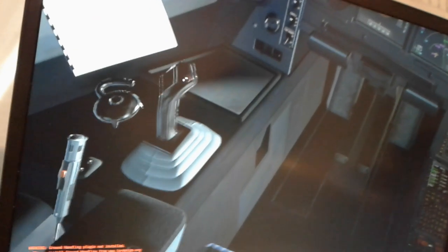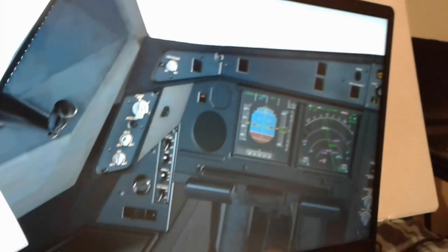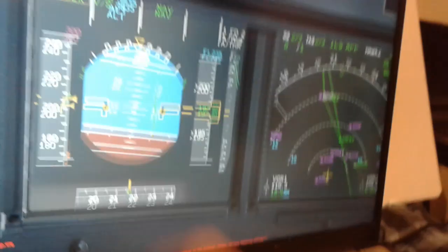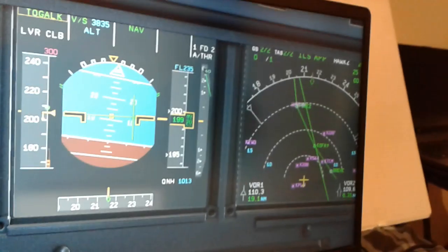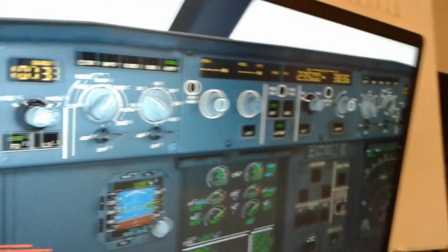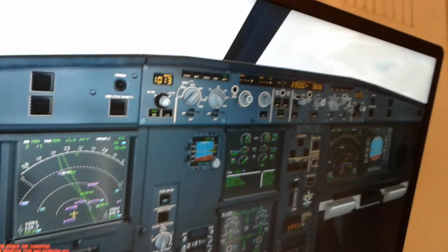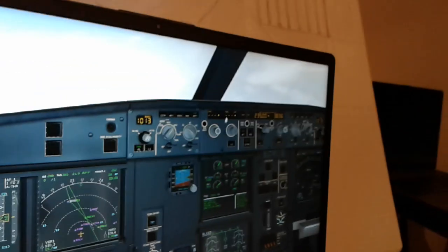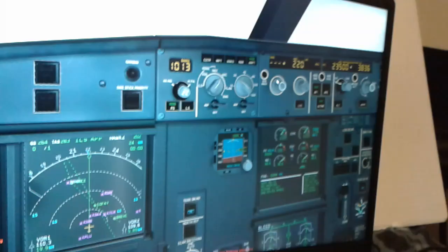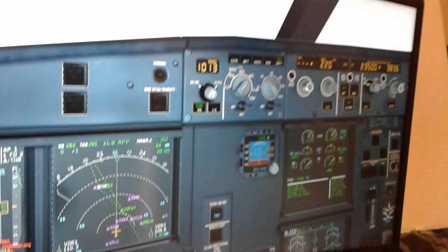So you can see the Airbus A330-200, the indicated airspeed, the calibrated airspeed. Now it's 200 knots, and we climb through 19,000 feet. We can connect the autopilot. We will follow the commands over here. Autopilot 1, cross check. We will follow the flight line, I believe. We can select the heading and the airspeed also.